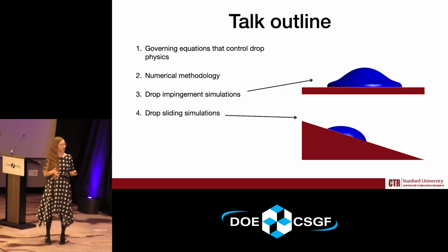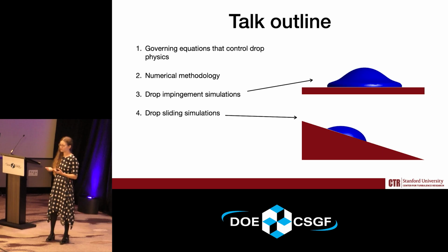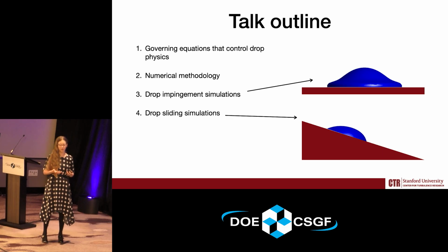My talk outline is I'm going to describe the governing equations of droplet physics, and then I'm going to go through the numerical methodology that I use to study these effects, and then we're going to go through some drop impingement simulations as well as some drop sliding simulations, and we're going to keep in our heads all of this rich contact angle physics.